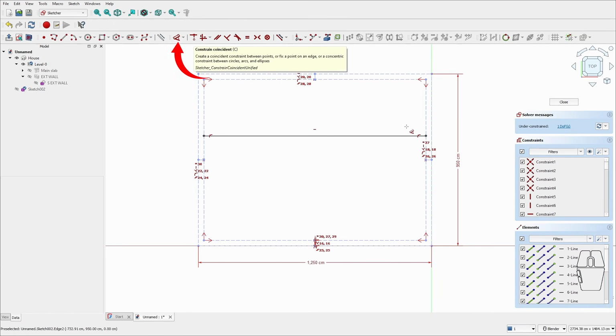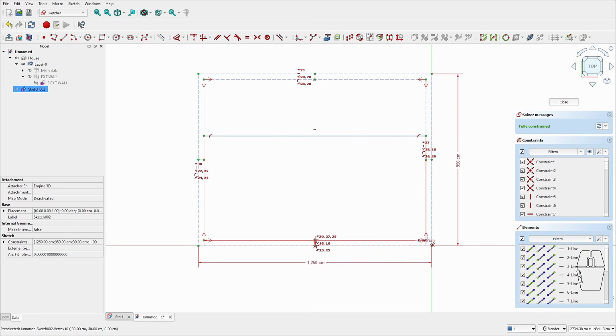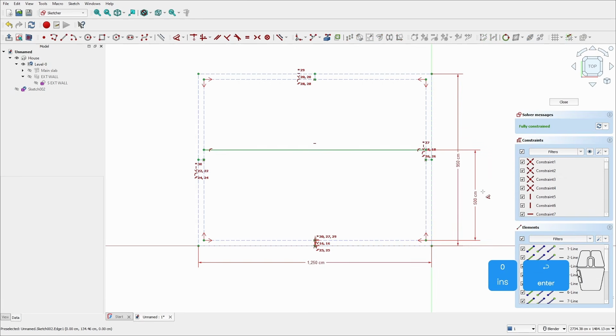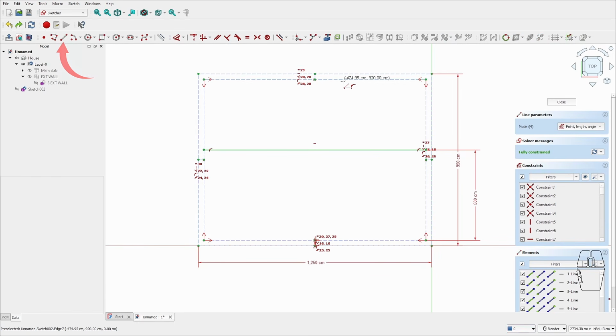With the dimension tool, give a height of 500 from the inside right corner of the dotted rectangle. Employ the line tool to create the separation between the bedroom and the bathroom. Start your line on the top dotted edge and end it on the last created line. Repeat the same process for the line separating the second bedroom and the laundry. Draw a horizontal line between the 2 most recently created lines to represent the corridor between the 2 bedrooms.